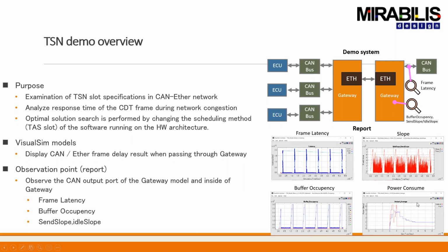Here's another one that might be useful many times, which is the power consumption. In addition to looking at the network, we also want to see what the power or energy impact of these performance decisions is. Just looking at the performance, which is your latency and throughput, and configuring the scheduler and the hardware platform to meet that would be a big mistake if your power is too high and your system can't handle the power requirements of the particular design. So looking at power is an extremely important attribute.